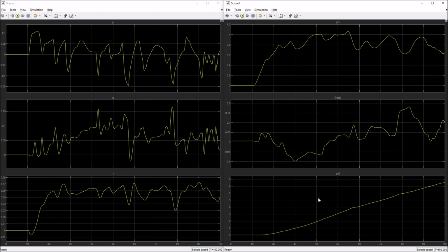So you can see, it's a little bit more intuitive to interpret what the Euler angles are doing rather than looking at the rate gyro information. If I look at the rate gyro information, it's a little hard to understand what the vehicle is doing. But over here, I can see that the bank angle is going to about 0.8 radians and it's kind of staying there, and theta is pitching up and down, kind of hanging around 0. Maybe it's got a little bit of nose up here, but the yaw angle is just increasing. So if I had to stare at this and guess what the aircraft was doing from the Euler angles, I'd say it almost looks like it's in some kind of steady turn, where the yaw angle is just increasing kind of linearly. So it almost looks like an orbit to me or something like that. So, this is pretty interesting.